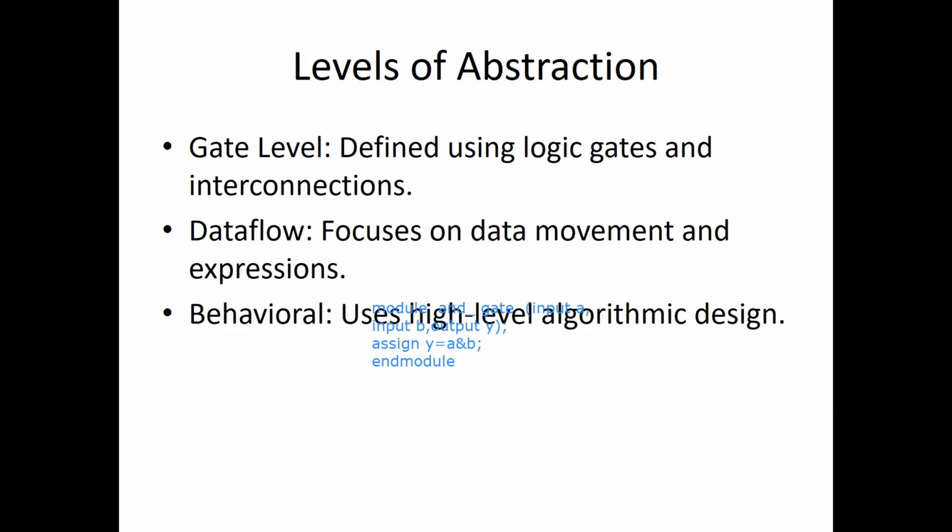So, what is gate level modeling? It can define the logic using gates like AND, NOT, OR gate, XOR gate. Gate level modeling is used when designing standard cells or when a schematic is already available. If the schematic is not available and it is a bigger circuit, then it is difficult to define which type of gate is used in a particular circuit. So whenever a bigger system is there and all the structural entities are already present, then you can use gate level modeling to design the particular circuit.